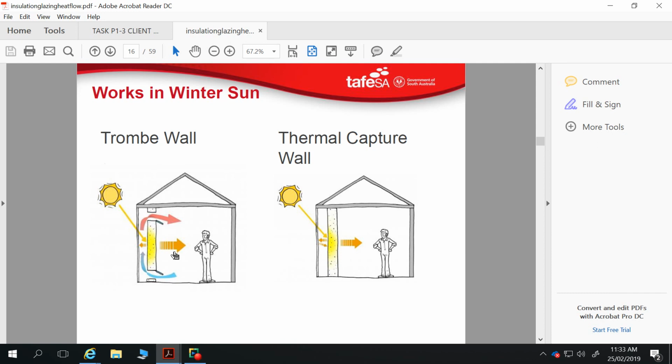Or also if you've got a lot of glass but you're on a suspended timber floor, there's no real thermal mass to the building, it can also be detrimental, because you'll be getting a lot of that sunshine in during winter time, but because you've got so little thermal mass in your building fabric, you lose all that heat very quickly, and then come 11 o'clock at night, the house gets quite cold, and by 6 or 7 o'clock in the morning, you've got a very, very cold, uncomfortable house, even though you've got your orientation and your glazing correct.